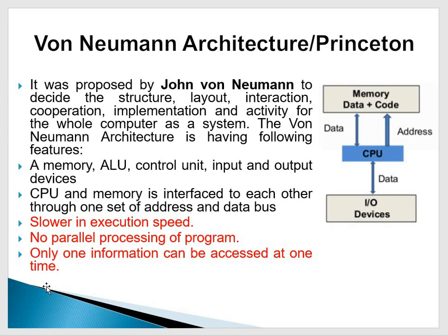What does it mean? The meaning of this is, for the normal process of the CPU, the processor will have to fetch the opcode from the memory, and once the opcode is fetched to the CPU, the execution unit of the CPU will be responsible to decode and execute whatever opcode is fetched from the memory.